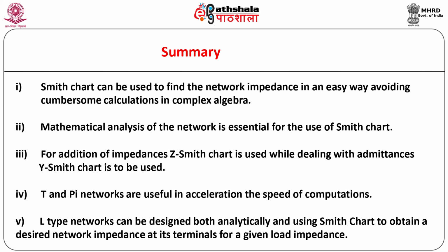The right half of the radius of the unit circle is used to measure VSWR, normalized resistance, Vmax, etc. On the other side, the left half of the radius is used to measure the normalized resistance, 1 upon VSWR, etc. Out of the circular scales, we can measure the phase angle of the transmission coefficient from the second circle.